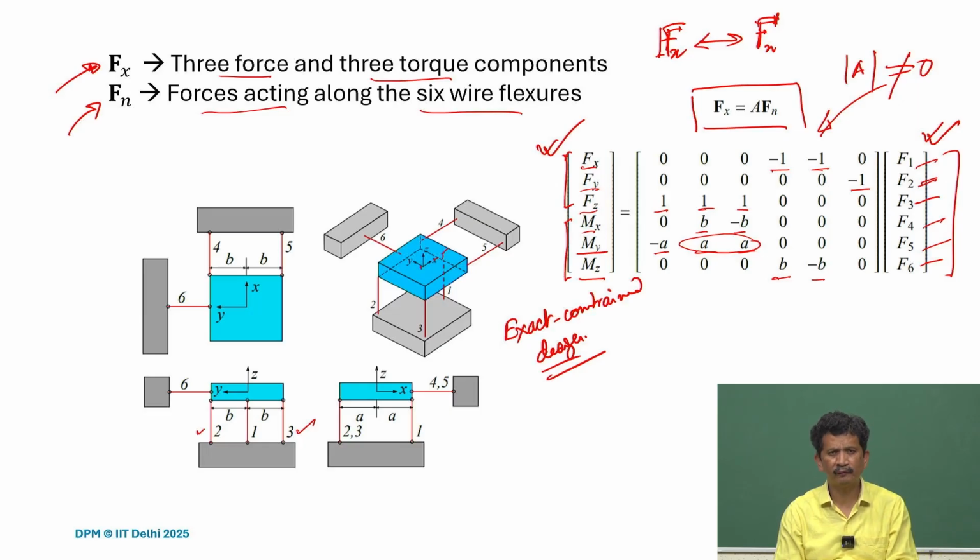One can also think of a Stewart platform, and we have worked on some examples, so I can show one example where we developed a 6-axis load cell, just using strain gauges and measuring in one direction, and it can be scaled up to any value. So those are things we can develop on our own, and they can be used and characterized. So this is very good, and this is the concept. Whether it works, we have to wait and see what results we got.